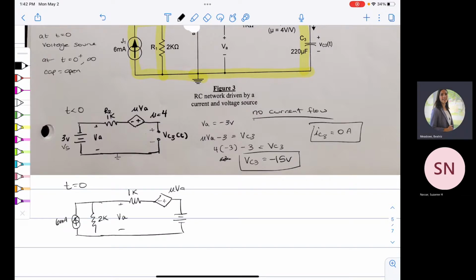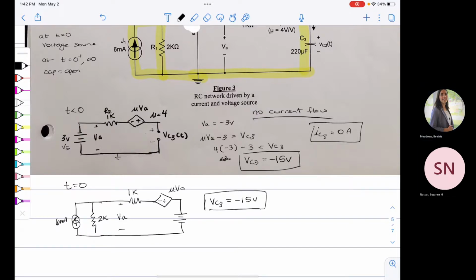All right. So what is our voltage at this time? And why is that? You're right. But why? Yeah, so capacitors resist change in voltage, so they don't have instantaneous changes. So remember how our capacitor is C dV/dt? So we can never have an instant change, because that's going to make this go to some infinite value, and it's going to mess up your entire circuit.